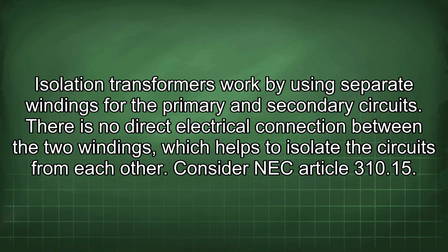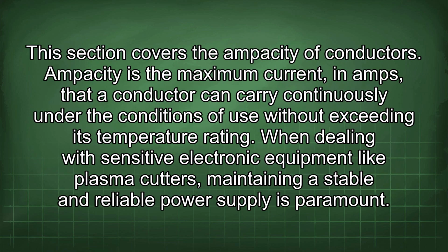Consider NEC Article 310.15. This section covers the ampacity of conductors. Ampacity is the maximum current in amps that a conductor can carry continuously under the conditions of use without exceeding its temperature rating.